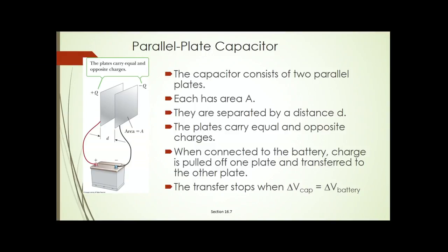So I'm going to be able to write and work problems looking at whatever my battery is connected to. I can fill up my plates and get that potential across those plates. If I have a 1.5 volt battery connected to 2 parallel plates, I get a 1.5 volt potential across my plates.